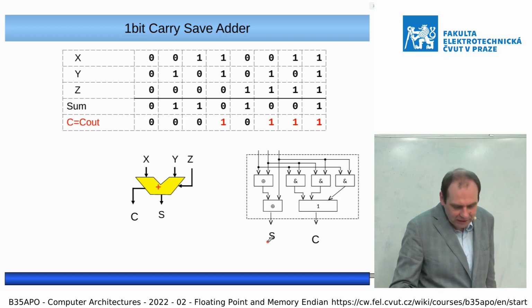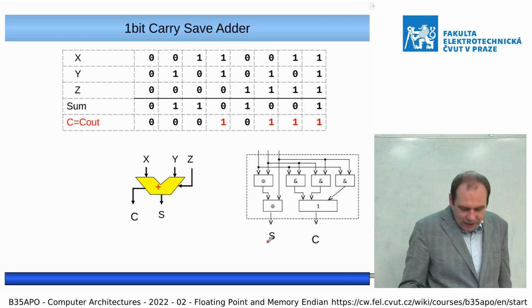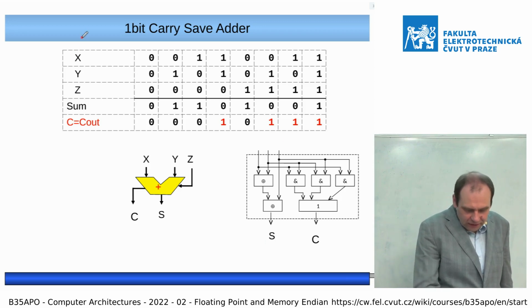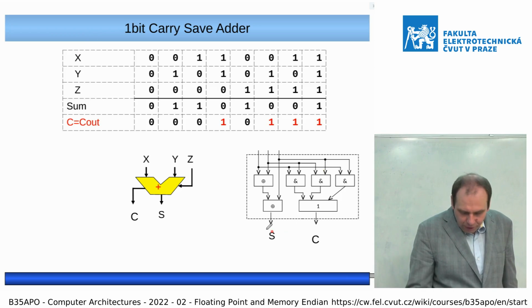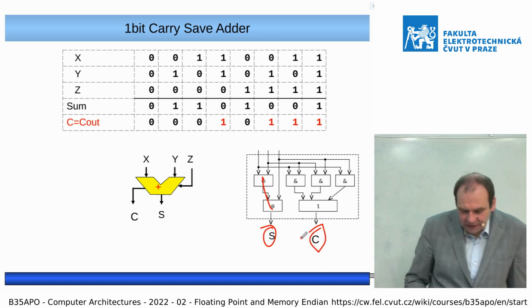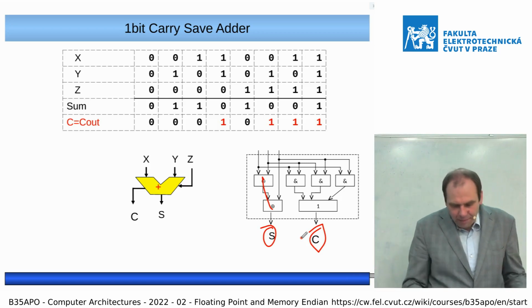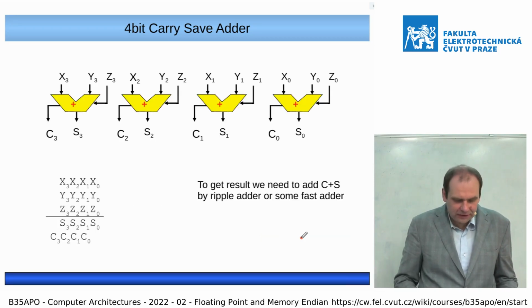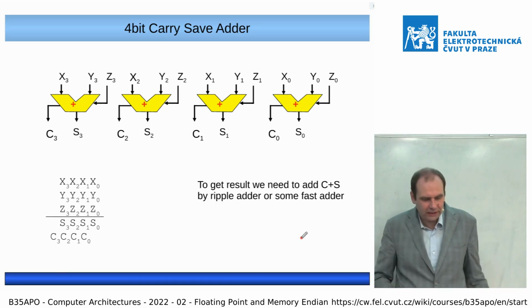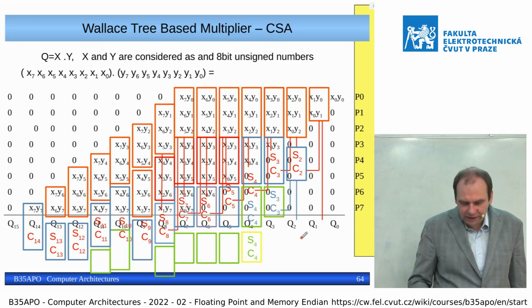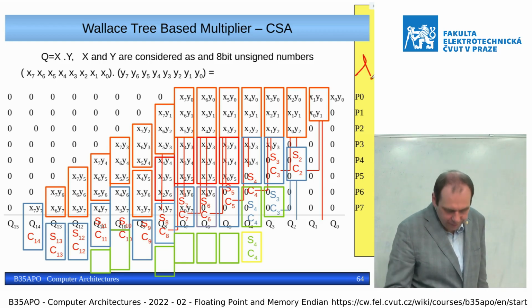So we can build this so-called carry save adder, which has 3 inputs, provides the sum value of a given bit, which is 2 XORs, and information if there is a carry in a given bit. But that does not take care of the rest. So it is easier because it is not the full carry chain. And then we can build this system of those partial carry chains. Again, it is not for the exam.